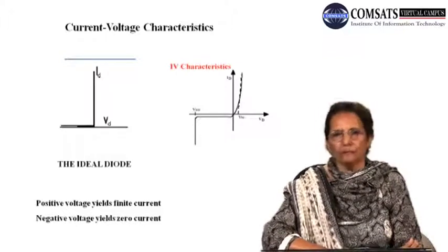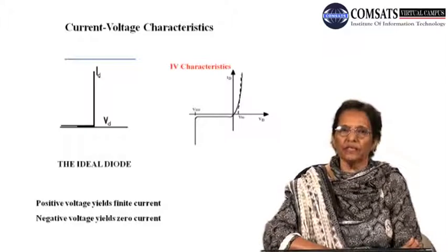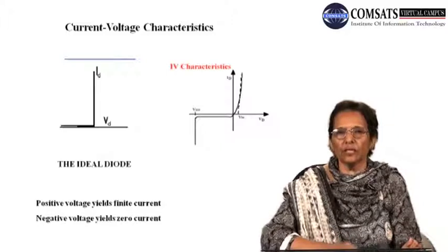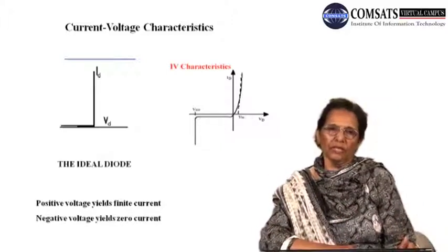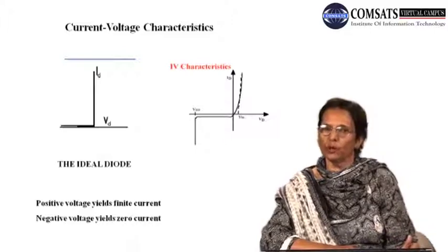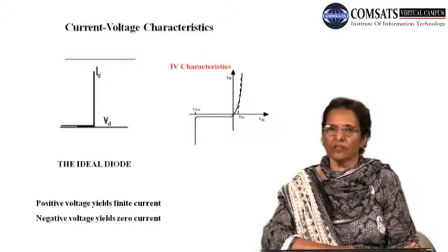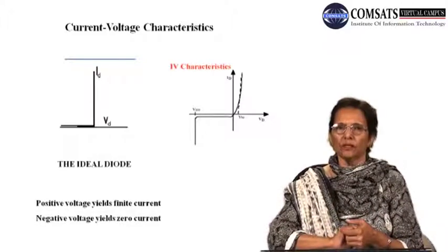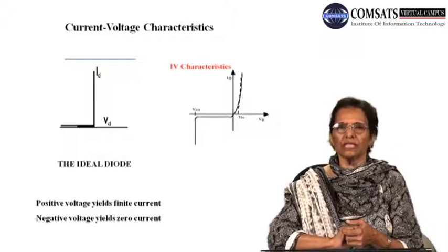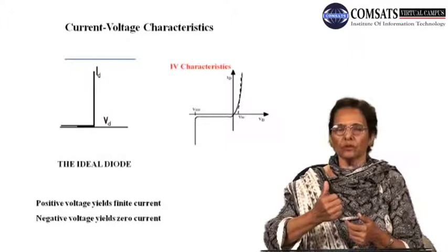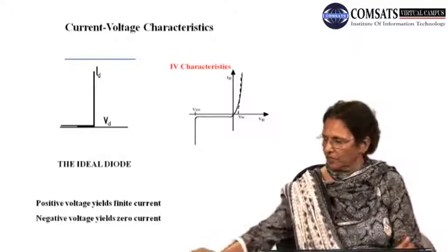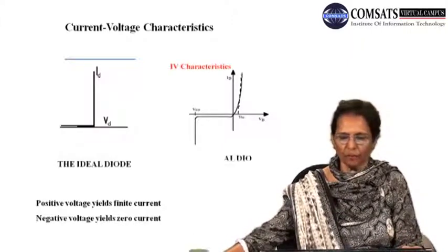There are special phenomena taking place at the junction breakdown voltage, BD, which we will not explain at this point, and will postpone the discussion of breakdown phenomena in greater detail to our later lectures. But let me just mention at this point the two phenomena which are responsible for this increase in reverse current. They are termed the avalanche breakdown or avalanche current, and Zener breakdown or Zener current. We will discuss that in detail in our next lectures.